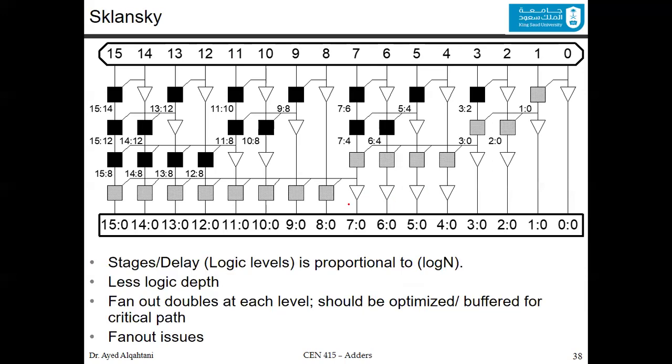And by doing this, the stages or the delay logic levels are now proportional to log n. So now the depth is shorter. So delay wise, it's even better. But it has less logic depth, as I said, but the fan out doubles at each level.